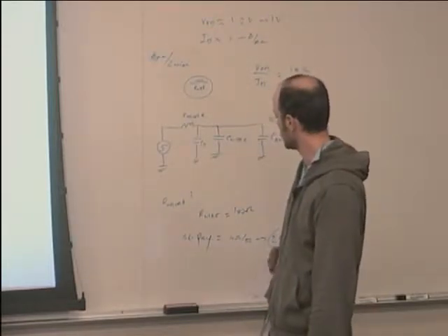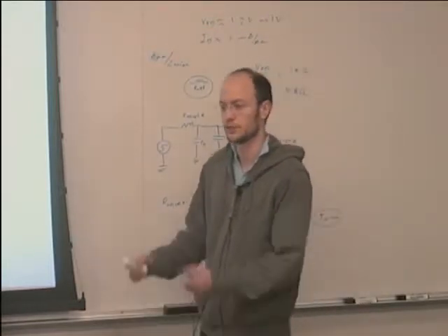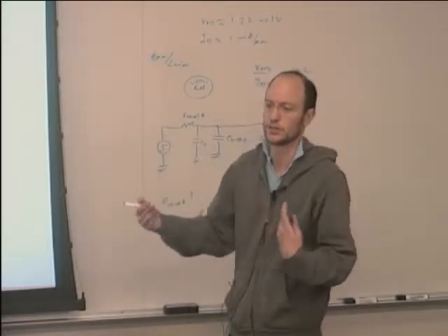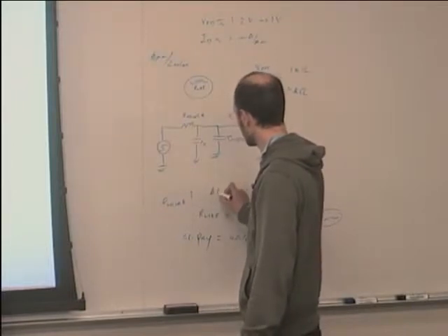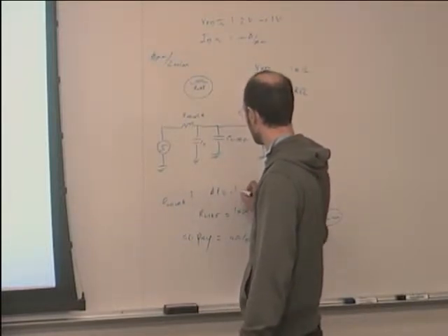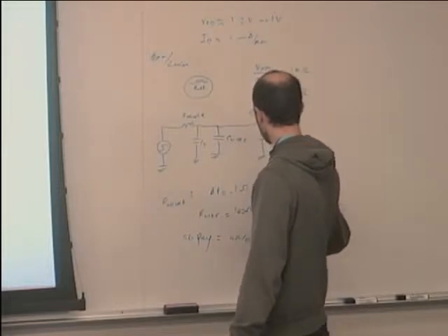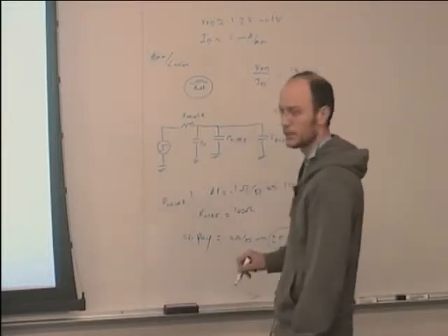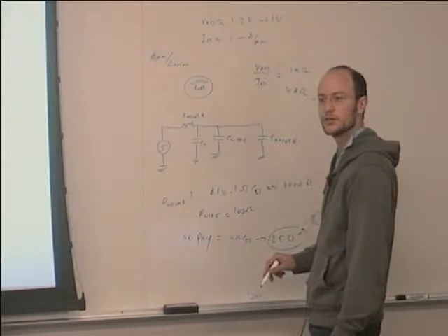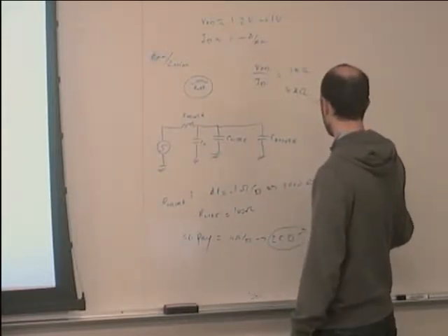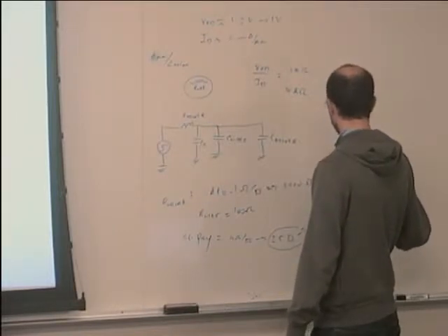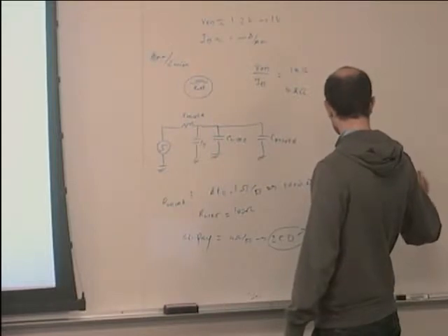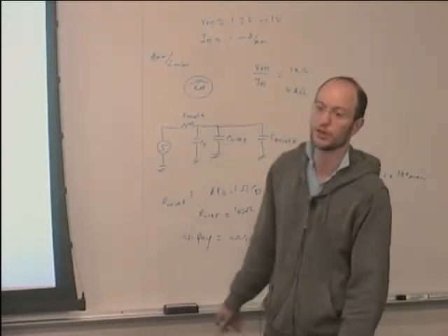So that's pretty significant. That's why you don't make these connections longer, right? And then if you're using aluminum, where we have, say, 0.1 ohm per square, you need 1,000 squares to get to 100 ohms, right? And therefore, you need a length of maybe 100 nanometer times 1,000, which would be 100 micron. So 100 micron is pretty long.